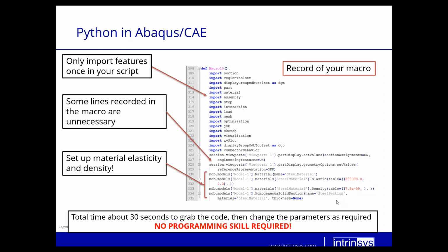What I would recommend is, as opposed to going to the manual and looking at exactly how to set it up, it's much faster and easier to just go back to CAE, maybe record a new macro, and define a material model with temperature dependence, let's say, with more than one line. Even if the numbers are irrelevant, just to generate the code.